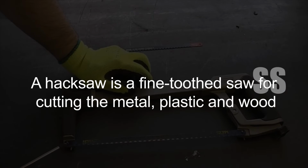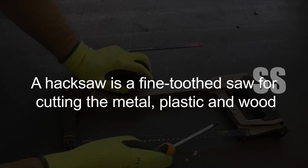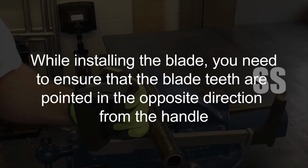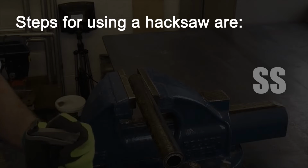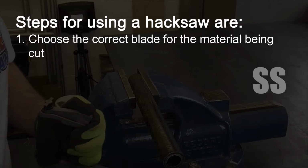A hacksaw is a fine-toothed saw for cutting metal, plastic, and wood. While installing the blade, you need to ensure that the blade teeth are pointed in the opposite direction from the handle. Steps for using a hacksaw are: choose the correct blade for the material being cut.